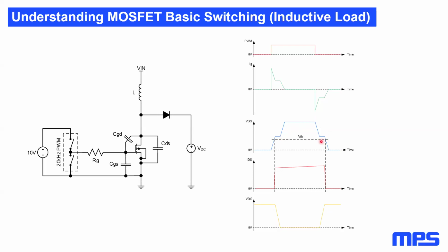The turn-off procedure for the MOSFET transistor is basically backtracking the turn-on steps. This starts with VGS being equal to the gate driver supply, and the current in the device is the full load current. A turn-off delay is required to discharge the MOSFET input capacitors from its initial value to the Miller plateau level. Once the drain to source voltage has been slewed, the gate voltage resumes falling from the Miller plateau to the threshold voltage.